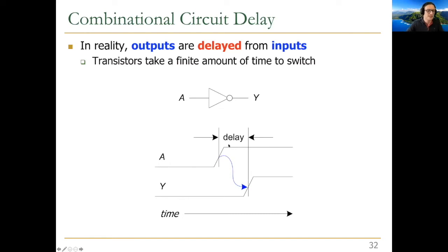And there are different definitions of the delay potentially, right? If you go into the analog part, you can say basically the 50% point of the, let's say, voltage. When do you get to the 50% point? That could be the delay, but it could be from the 10% point to the 90% point also, in the analog range of the voltage that you apply to the circuit. You don't need to worry about that at this point.